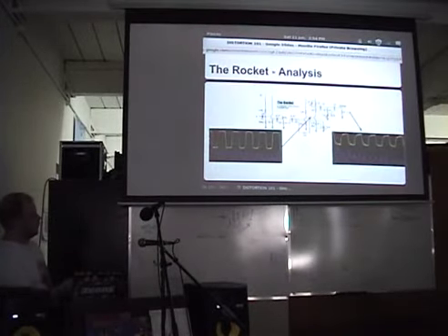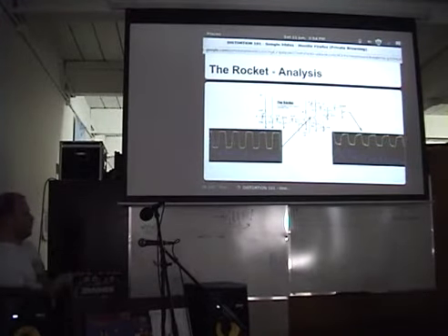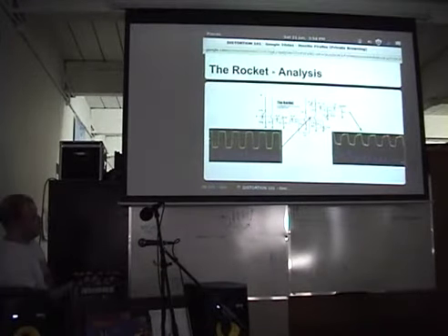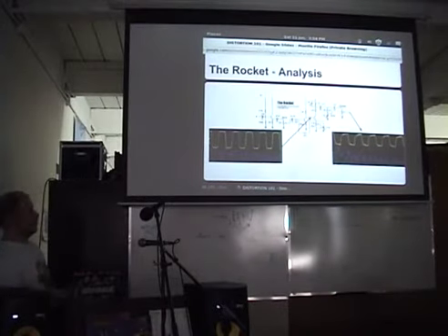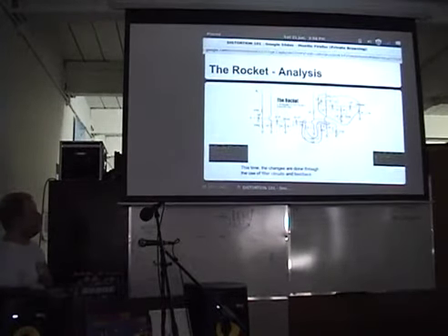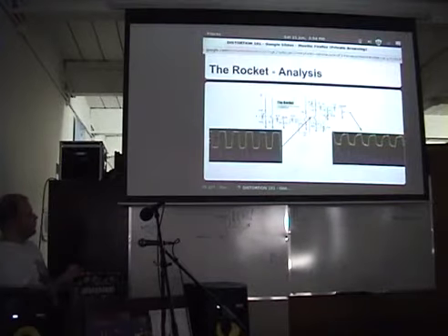Further, this stage is tapering them off. This is on a logarithmic scale. I could have made a better diagram, but I didn't. So you can see the output levels at the top end, the high frequency spectrum, are tapering down a little bit here, which mellows out the sound a little bit. So that's what these bias circuits do, is what they're known as, bias circuits.